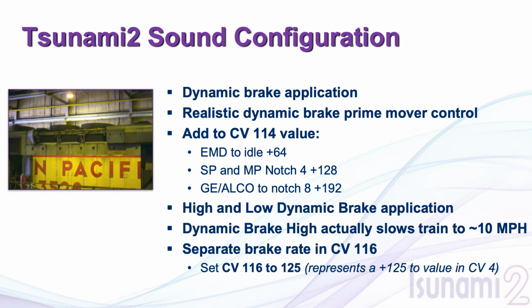Locomotive engineers introduced dynamic braking, and what this does is take the electric traction motors that are located down on the trucks and turn them into electric generators. That electrical energy is generated and causes a slowing of the wheels through the traction motors. That electromechanical resistance is what slows the train and tries to help keep it under control. So rather than using brake shoes, you're using that regenerative braking.